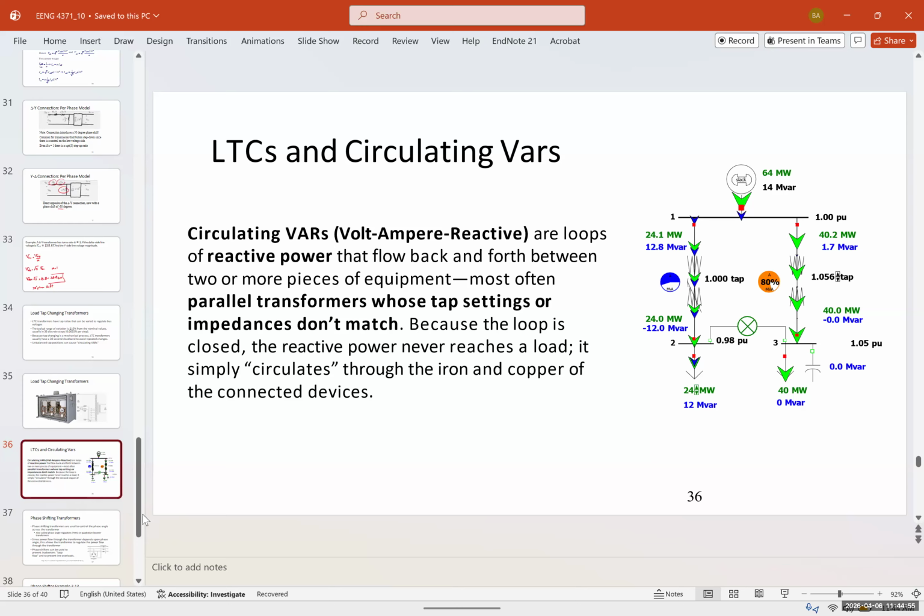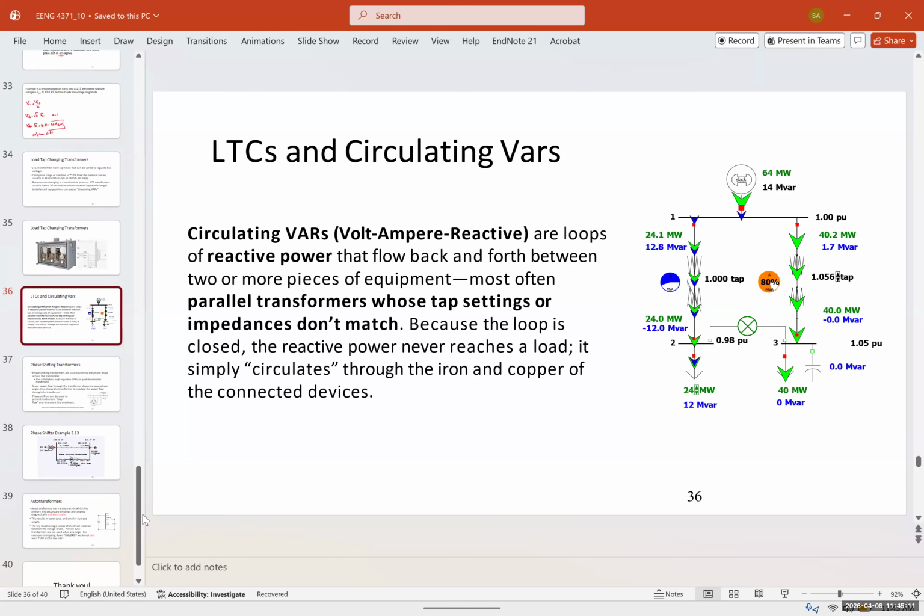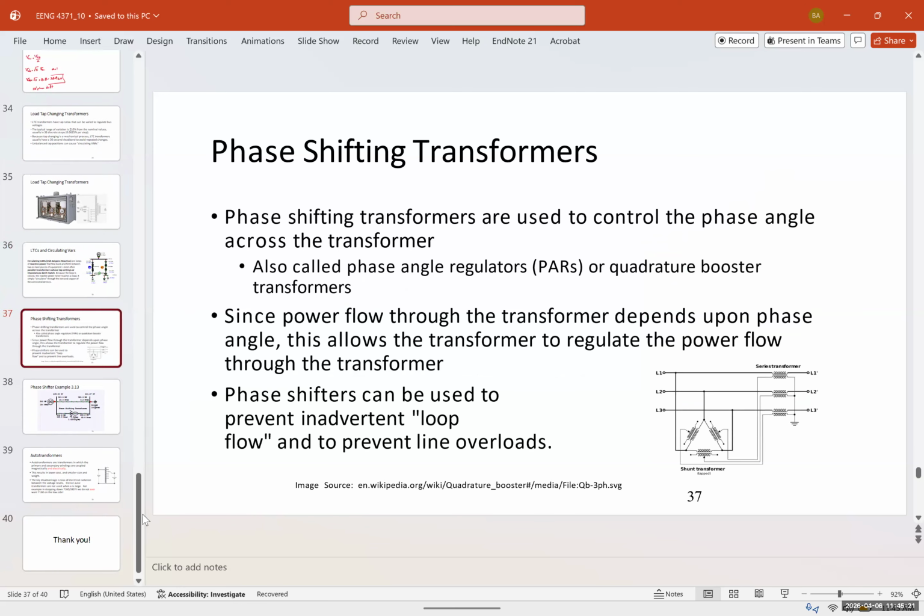It's because it's a volt amp reactive. It's not real power, it's reactive power. And this reactive power is wasted through the system via heat. So it may cause some damage. So we have to be able to counter that. Then we can use power capacitive banks and so on to be able to compensate for that.